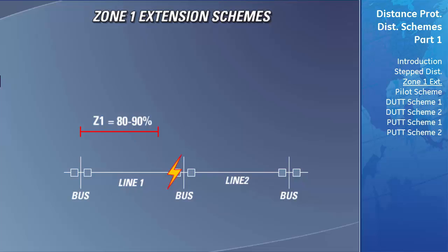If the fault fell inside the transmission line's end zone area, the permanent fault would then be cleared by the Zone 2 protection after the set time delay. If the permanent fault were picked up by the D60's Zone 2 because it was located at the beginning of the next adjoining transmission line, the relay protecting that transmission line would pick it up in its Zone 1 area of protection and clear the fault. The D60 will then continue to use the shortened Zone 1 area of protection until the auto recloser sequence has expired. At that point, it will revert to the extended Zone 1 area of protection.